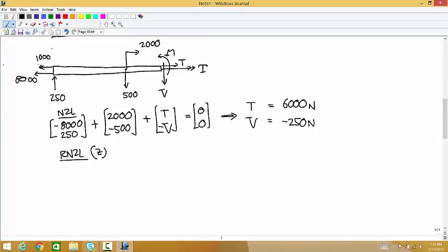Okay, so the moment about z produced by that 500, it's a moment arm of a quarter meter times 500, and if this is the about point, that would be a clockwise rotation. So that's negative 125 plus m minus v times, I guess that moment arm would be 0.375, is equal to 0. So m is equal to, what's 250 times 0.375? 93.75.